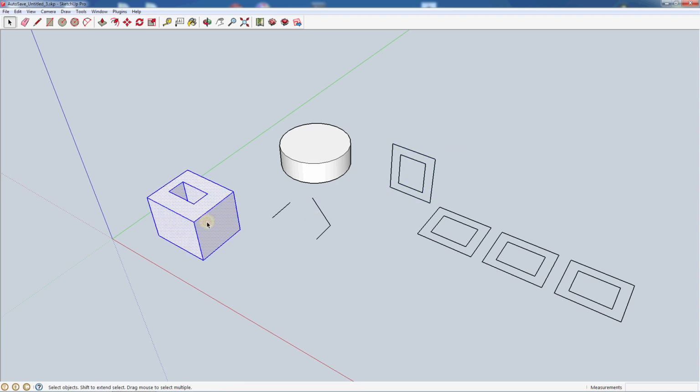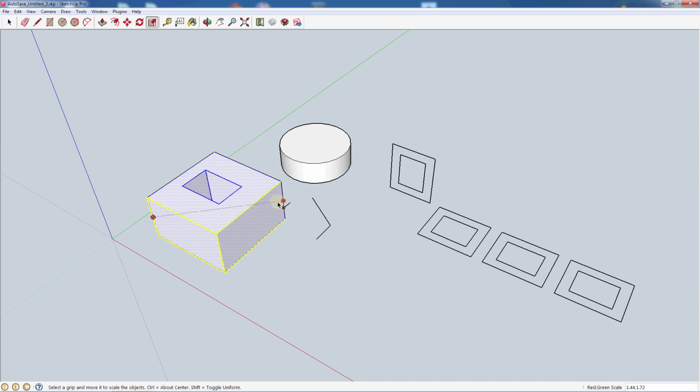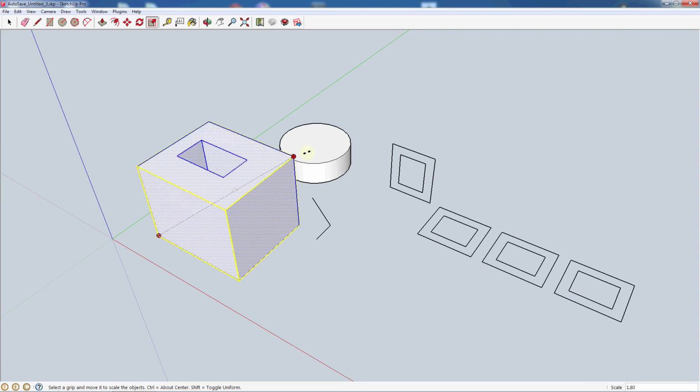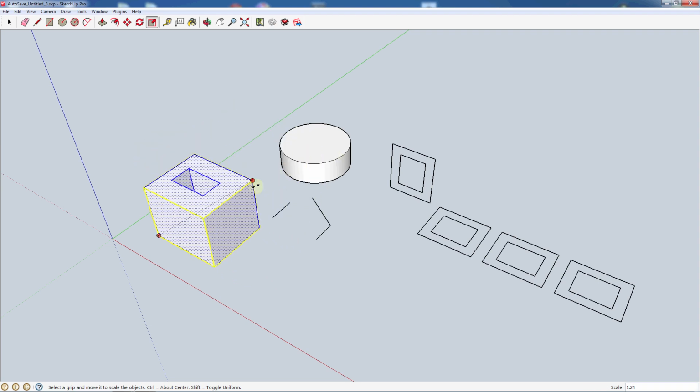Now, if we come over to a 3-dimensional object, you're going to have even more points to select from. As you see here, you've got 8 on each surface, and depending on which one you grab, it will scale in. Here it will scale red and blue. Here it will scale just red. Here it's a uniform. Here's green and blue. So you kind of get the idea that it's going to scale certain objects or certain faces and planes, but not the other. So you also can manually select down the lower right the size of the scale. So it starts out at 1. So if we grab it, we're at 1. And we can manually slide it going up to a point. Here's 1.5, down to 0.5. Or we can type in 0.25, and that would be a quarter size.